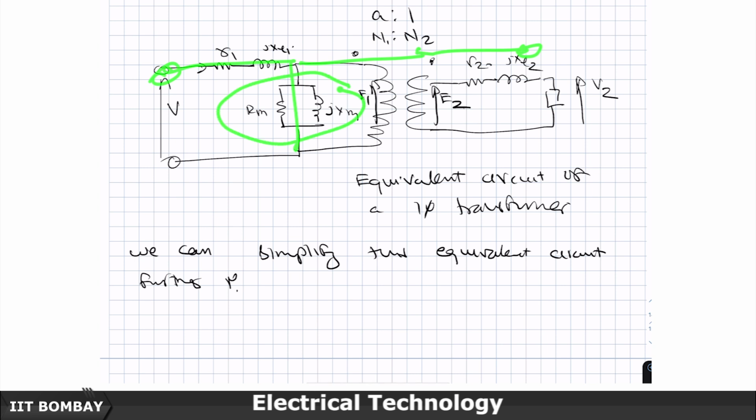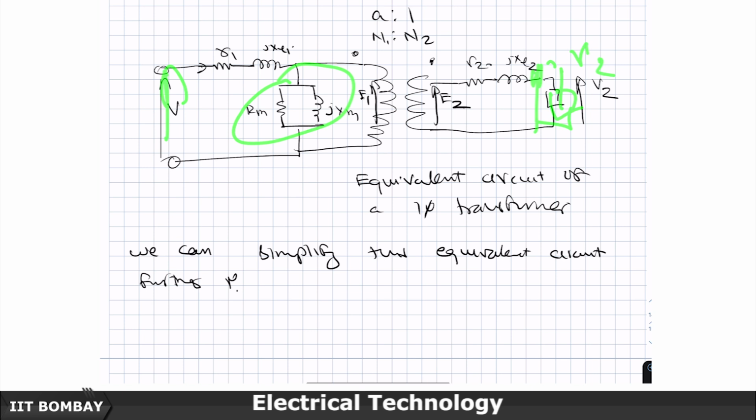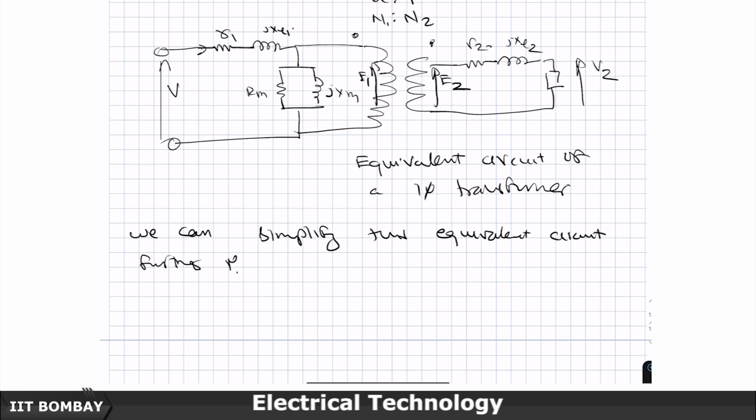And then we are going to say that because the no load currents are so small, for normal day to day work, like if I apply this voltage here, if I connect a load here, what is the voltage here, do I really need to model this 1 to 2% small current? And the answer would be, no, not really required. So, later on we will do a simplification that many times we can ignore this one also. But first thing first, let us see the trick of how we can eliminate this ideal transformer.